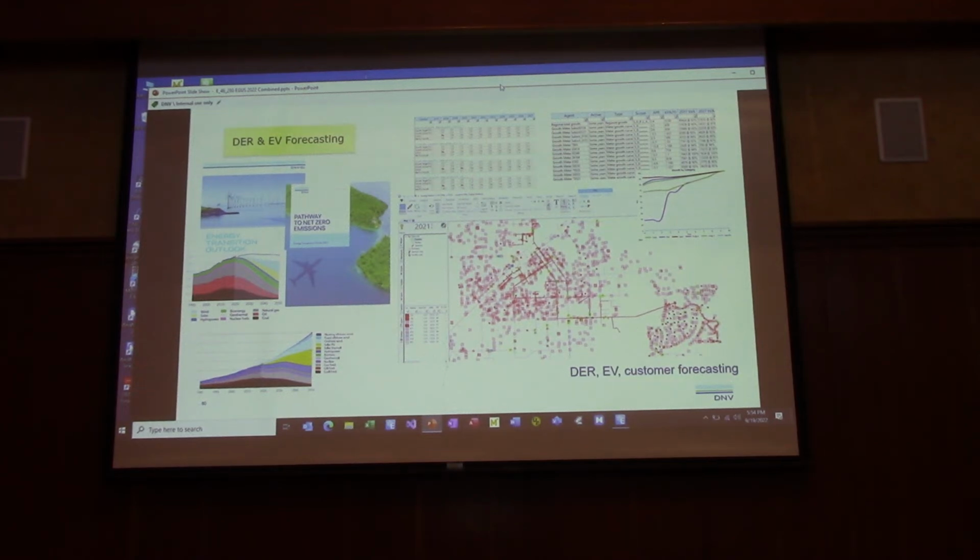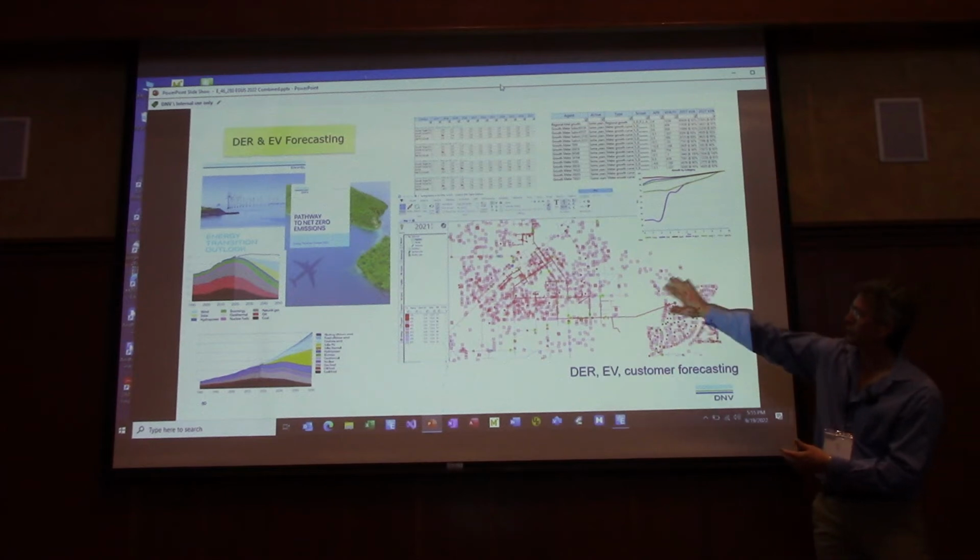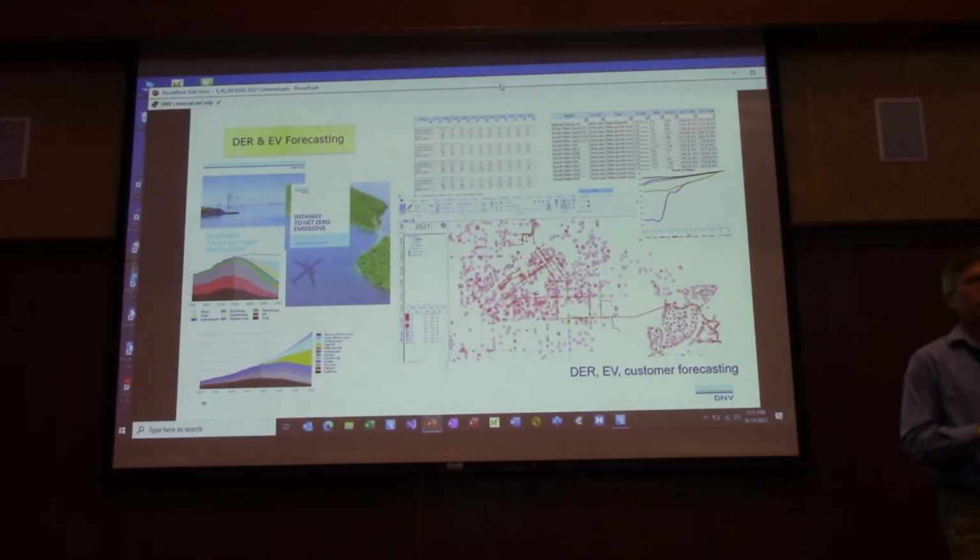So we do have a load forecasting application in Synergi. It's on the planning tab. And there's different ways you could set up growth and things for forecasting. We're going to do PV forecasting. There's lots of ways in Synergi now. We'll do it the DER session where you can put PV on the model, but it's just kind of bland. It's just some very crude approaches. We want to start getting customer information, econometrics, other sorts of data in here that we can use to give more sensible locations of PV.